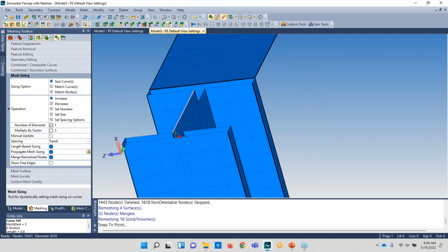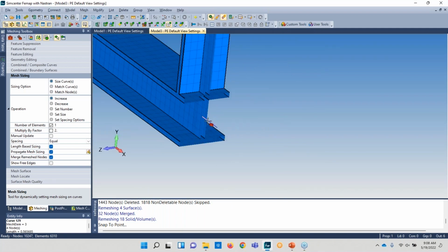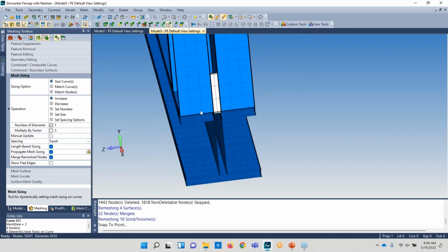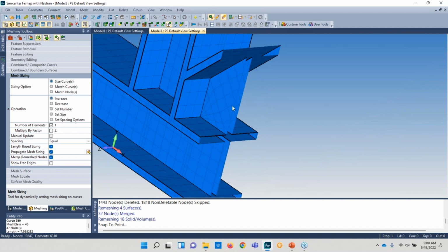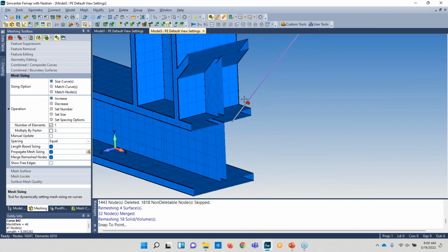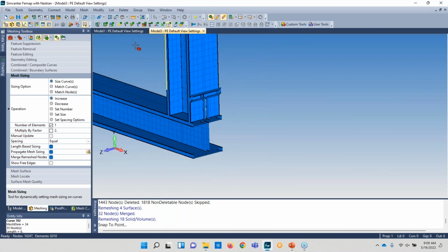So here, when we peek inside, it looks all hollow because it's only drawing those free surfaces. As we come over to this region here, there's a little bit that didn't quite get merged in with the rest. So this is better than it used to be, but you can still see it's important to know some tools to check your mesh and merge your nodes.